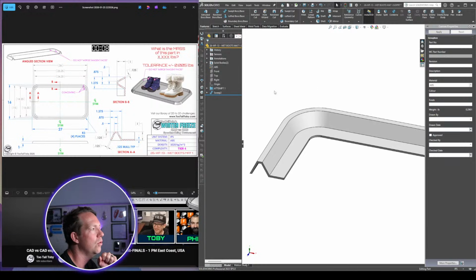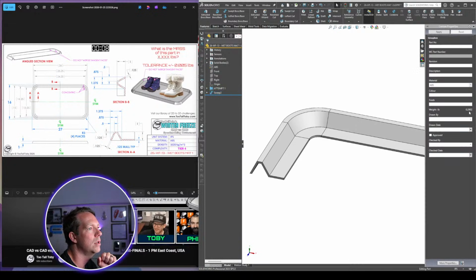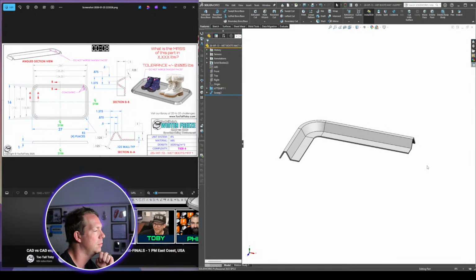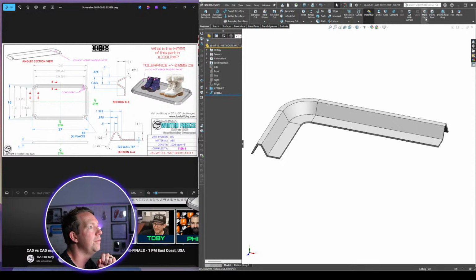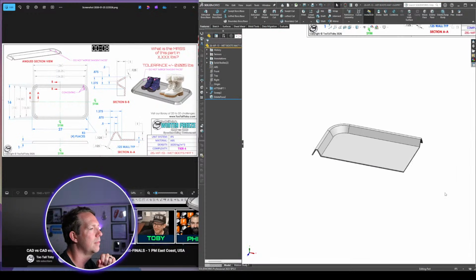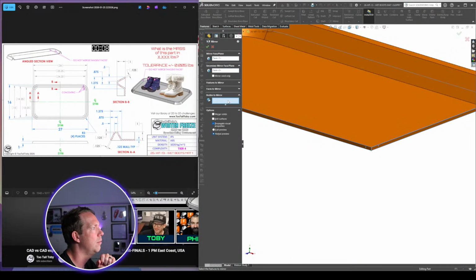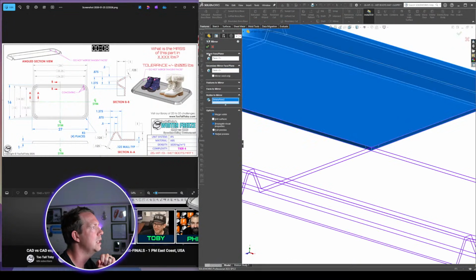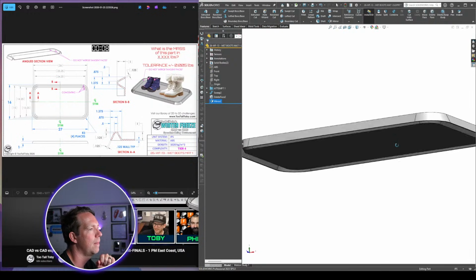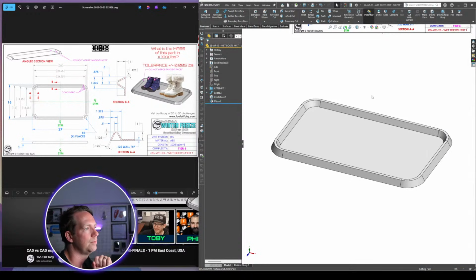It says 0.2901. Uncheck. 0.2902. Minor difference. Right, to fill in the bottom, delete face. Even select tangency, okay. And then double mirror. So mirror, mirror, body, merge, tick, done. The correct answer, 2.312.